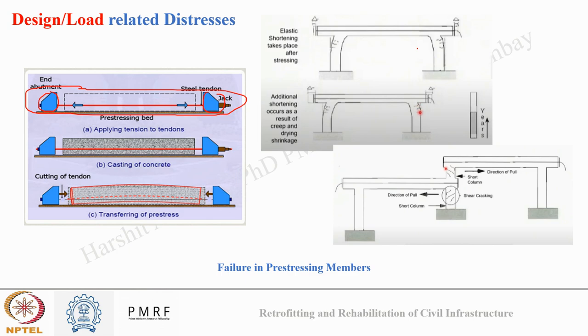And you can see the same in the images also, how crack is growing near the joint when the stresses are released. And in this image also, you can see a pre-stressing member, and when they are released, how cracking happens. So again, the remedy can be provided by doing proper designing of concrete and taking care of the released tension force that can act on the concrete member.